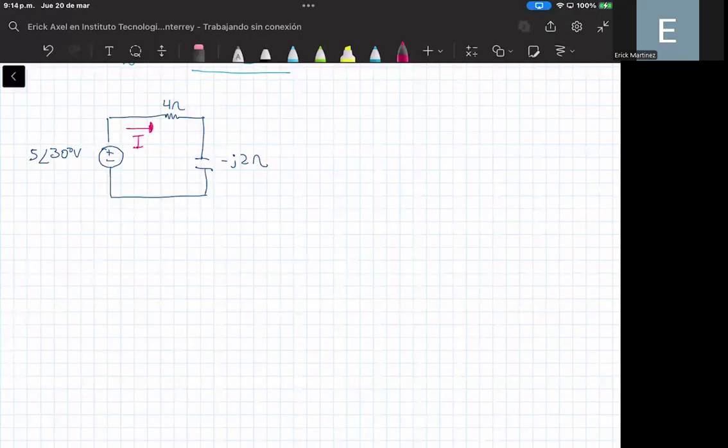Okay, so in this video, I wanted to show you how you can compute the average power in an AC circuit. One of the reasons that we want to study the average power that is supplied to a load is that we prefer to compute that instead of the instantaneous power, because instantaneous power changes with time. For example, you can plot the power of an AC circuit, and since here we have a sinusoidal behavior, we can expect that the power could also have a sinusoidal behavior, and that power will be changing over time. And that complicates analyzing a circuit because the value is always changing.